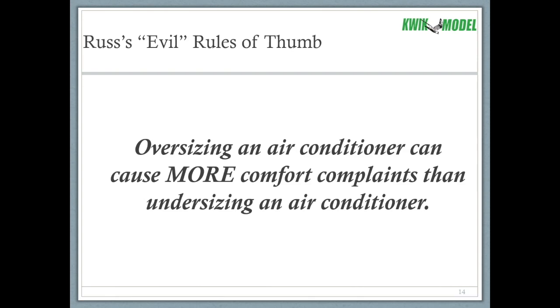Most of the comfort complaints that I deal with, those systems are oversized. It's a combination of undersized ducts and oversized air conditioning equipment. It just leads to all kinds of different comfort complaints, and people will tend to think, oh, it must be undersized, that's why I'm having these complaints, but the problem is actually that it's oversized.